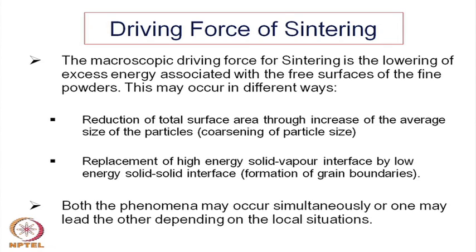So, there must be some driving force, as all this happens just by heating the material to a high temperature. Something must be happening, and there must be some processes taking place for which there must be a driving force, a thermodynamic tendency for the changeover to take place. So, the driving force of sintering can be mentioned in this manner. The macroscopic driving force for sintering is the lowering of excess energy associated with the free surfaces of the fine powders.